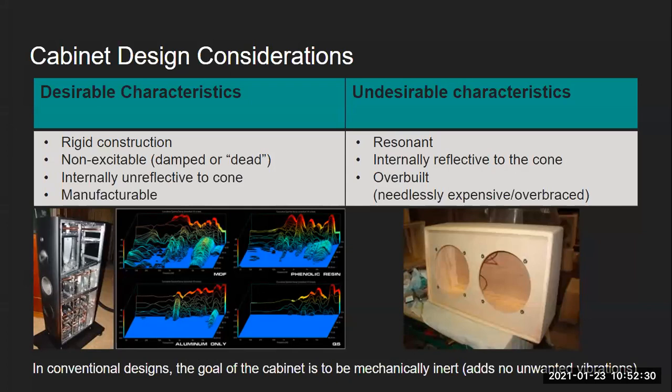If we just had that vibrating in free space, for any wavelength larger than the diaphragm, it's going to start wrapping around and canceling because you have 180-degree inverse coming off the back of the speaker. So what the cabinet's doing is providing a certain amount of separation to allow for those frequencies not to be canceled, so you can play down into those lower frequencies.